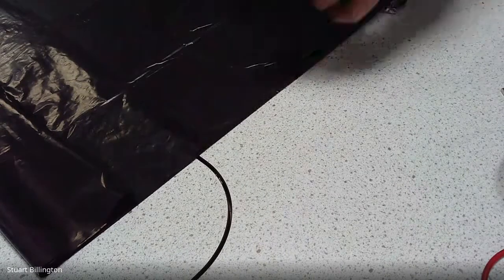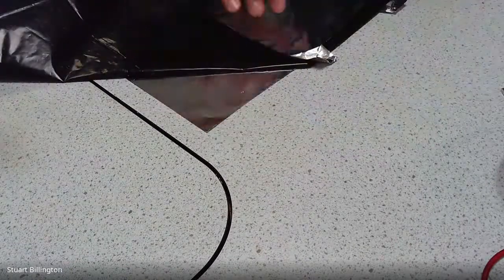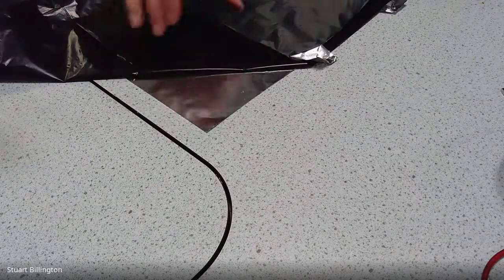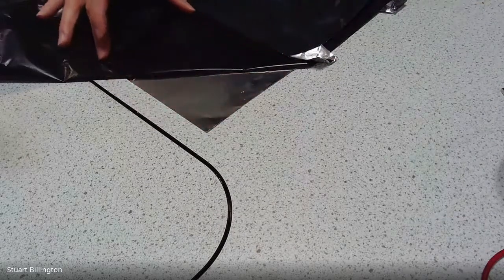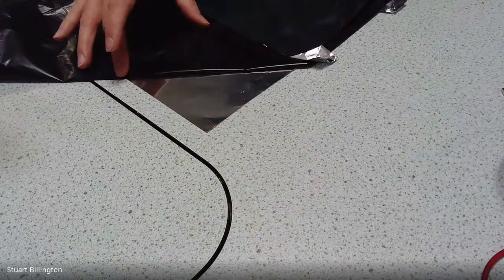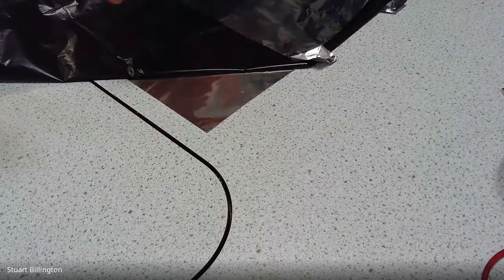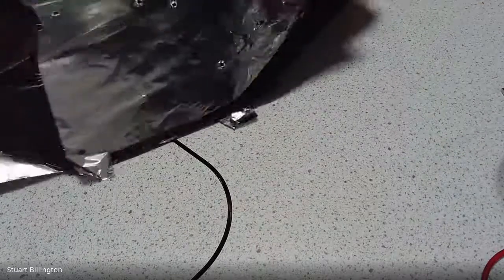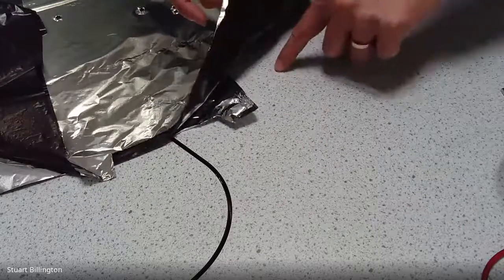But if I were to take this top plate and move it a little bit so that they weren't overlapping fully, so that there was an area here without any overlap, then what we would find is that this positive charge here would have no negative charge above it. And likewise, over on the other side of the capacitor, this negative strip here would have no positive below it to attract it.